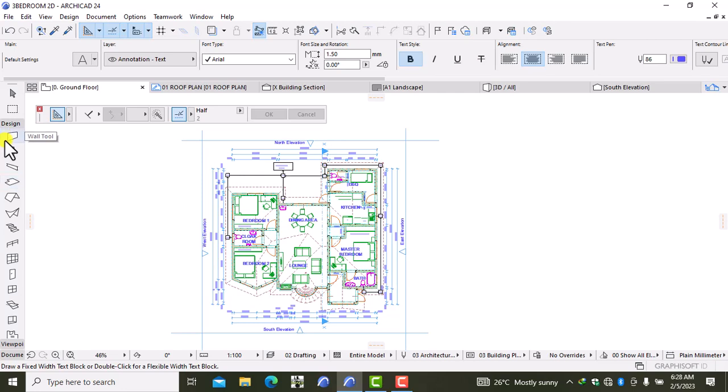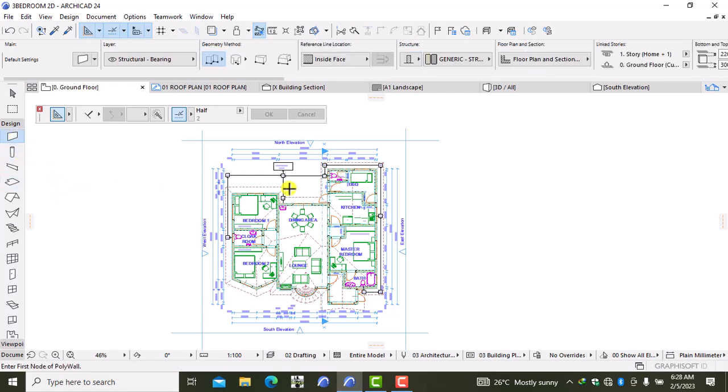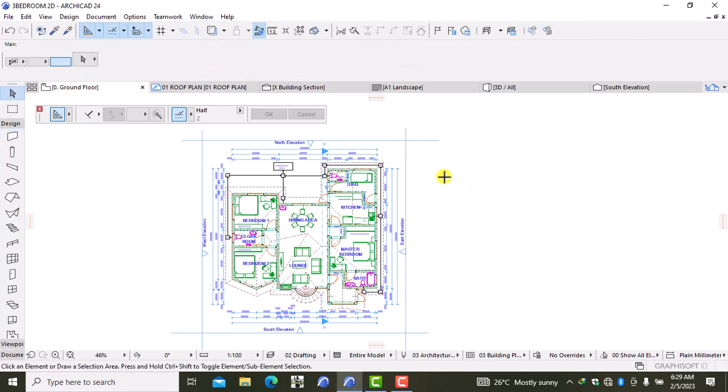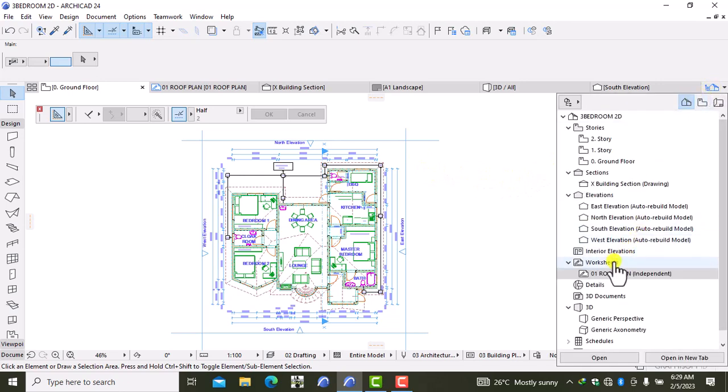In order for you to come up with the site plan, you should have visited the site, see the accessibility of the site, where it's located. So in order to come up with the site plan, you should look at the roads nearest to the plan, maybe the institutions that are close to the plan, maybe it's near a school that's well known.